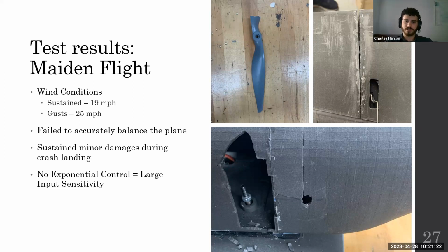The only real pre-flight tests that were conducted were control surface deflections and whether or not they were deflecting to the right extent. But other than that, it was a large oversight in the maiden flights, the lack of pre-flight inspections and testing. That was later corrected in our other flights. Adding in, we did do a wingtip test to confirm the deflection of the wing, and we also tested the landing gear to see how much it deflected.